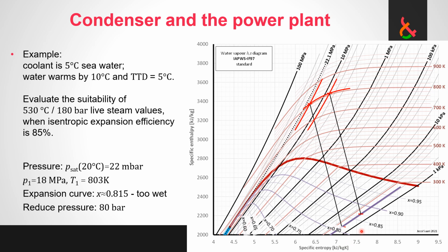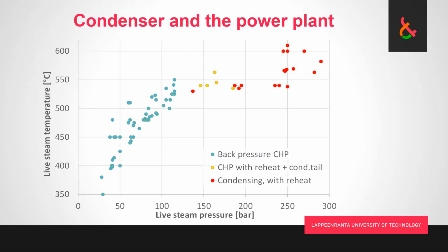Now in your course assignment, you want to have a little bit drier steam, rather more than 90%, because part 1 of the assignment is going to be the basis of part 2, and you're going to have problems in part 2 if you get too wet steam already at this point. So try to have 90% and a little bit more. That should be a good value, and this is an easy way to do that. So basically, as temperature goes up or down, the pressure follows it.